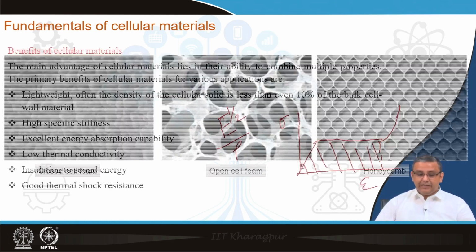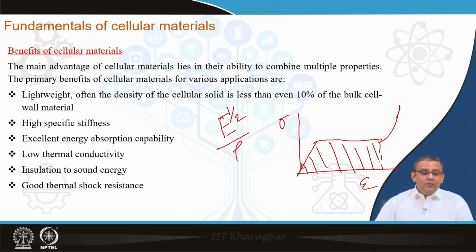Some cellular ceramics are also useful. Ceramics are very poor in thermal shock resistance, because they typically have low fracture toughness and also a high Young's modulus. That means if a ceramic material is shocked from a high temperature to a low temperature, it is very prone to failure or cracking.